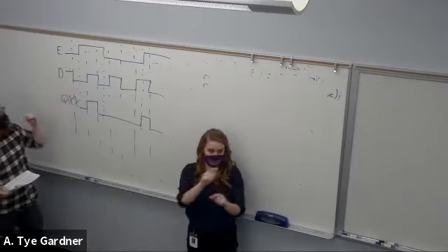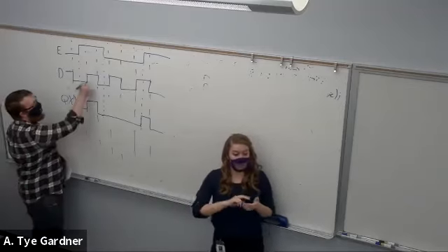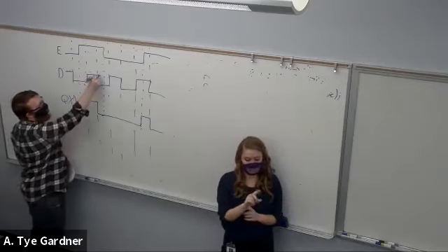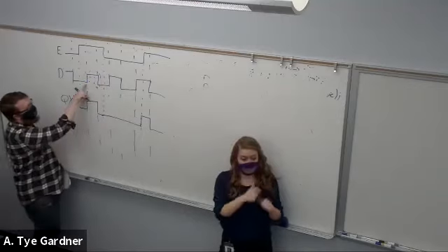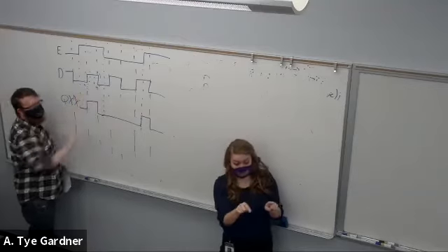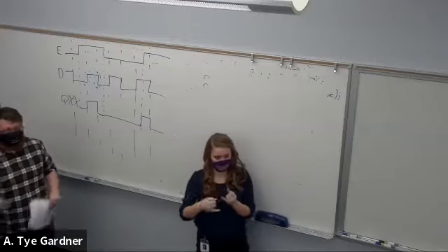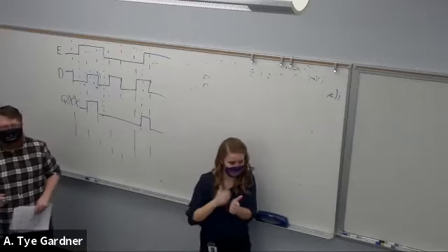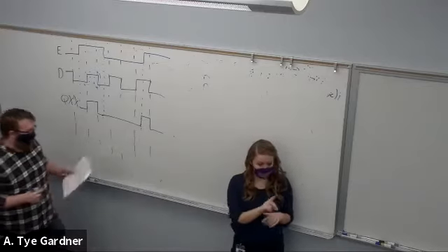And we're going to do it as edge triggered, meaning it's going to happen at the rising or falling edge only. So rising edge is 0 to 1, falling edge is 1 to 0. That's the only time these digital circuits are going to update. How do we do this? How do we make that happen? Well, we just take the D-Latch and make it a little more complicated.